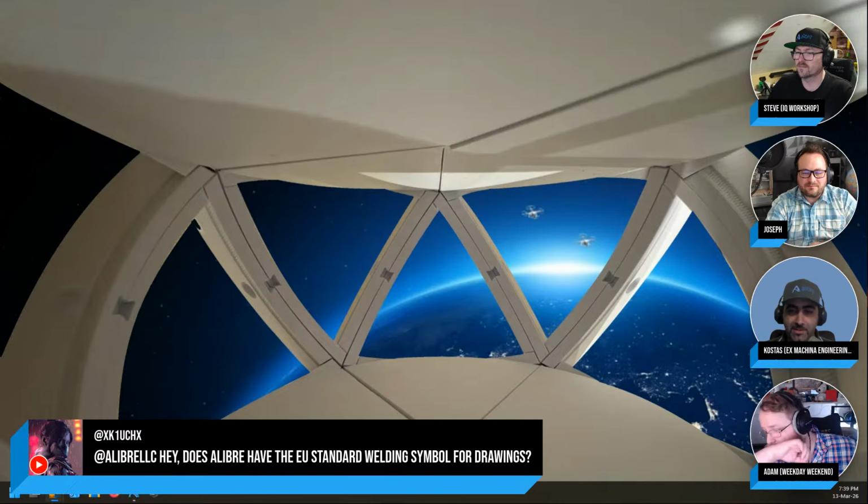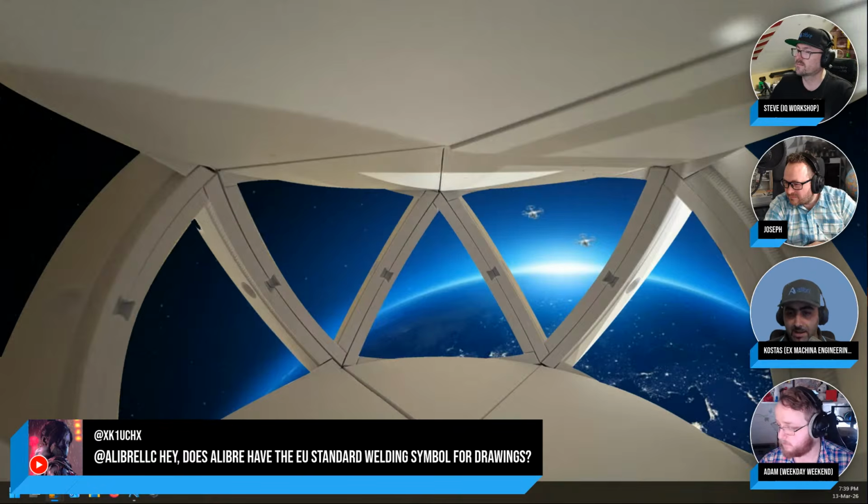That's a top tip right there, and that's also a tip if you're making any sheet metal part, guys. Bend radii and reliefs and all that. Most shops have a set of rules for that. For example, if you're using a 2 millimeter thick sheet, then you'll be using a bending tool that has a 1.2 millimeter radius.